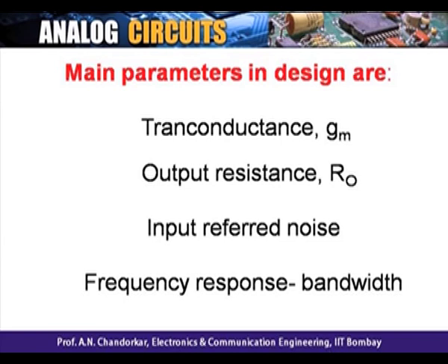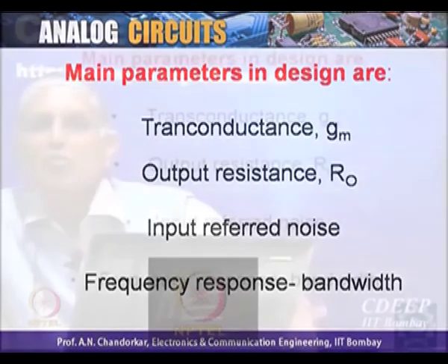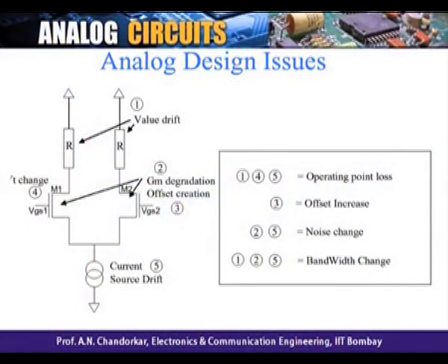And fourth, the most important part other than the gain, is the bandwidth. The larger the bandwidth, the higher the frequency performance, better, and therefore larger bandwidths are desired. We'll see a very interesting thing will happen. Gain into bandwidth normally is constant. What do I say? Gain into bandwidth is normally, in quotes, constant.